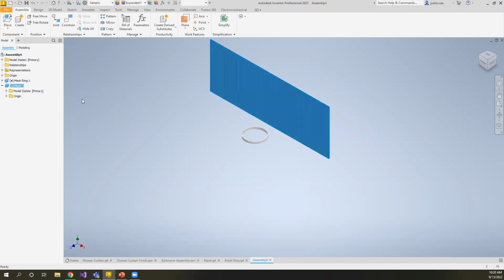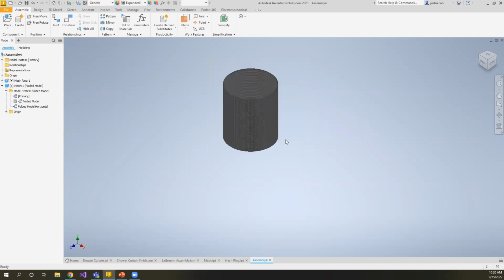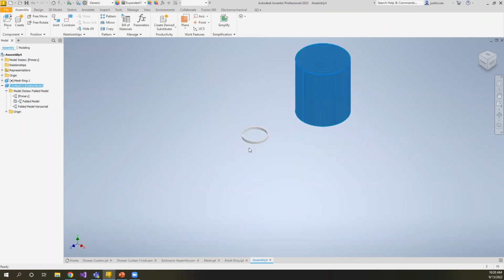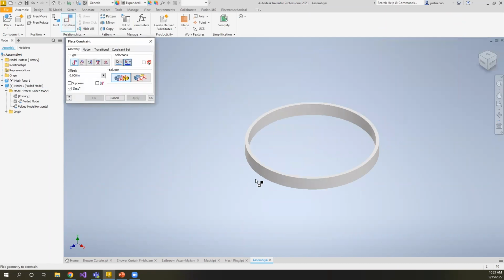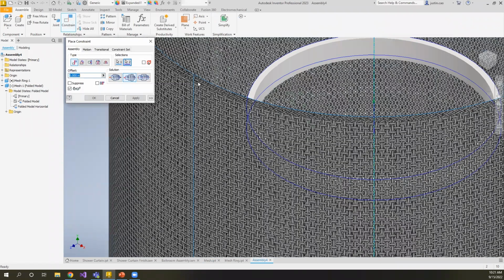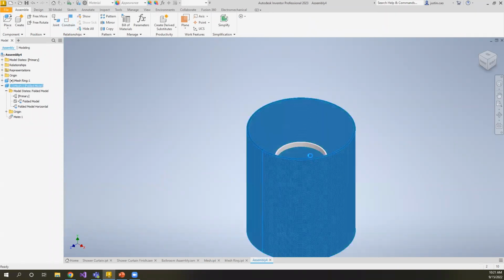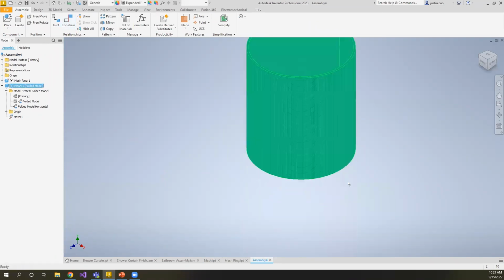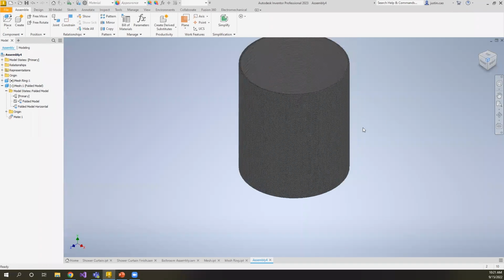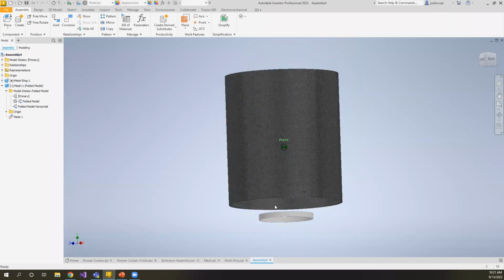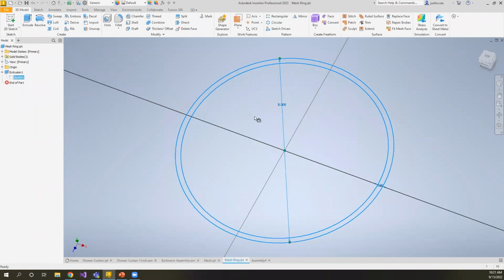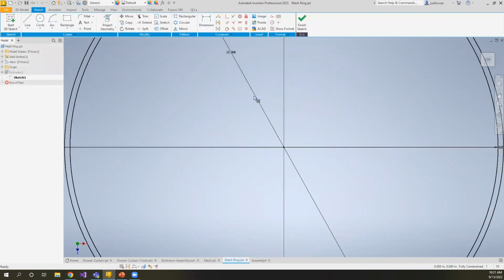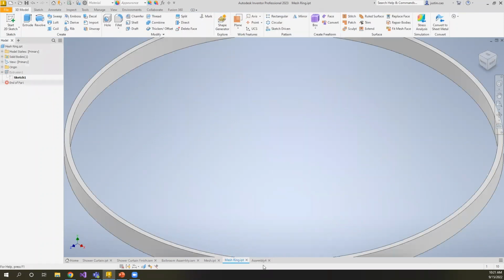In this case, we know that we want to bend it to match the ring. So I'm going to use this folded model, and you're going to see that I'm going to be able to constrain it to that. In that case, I think I made my ring too small actually. So let's go back and change that real quick. Radius was 5, so it actually needs to be 10.